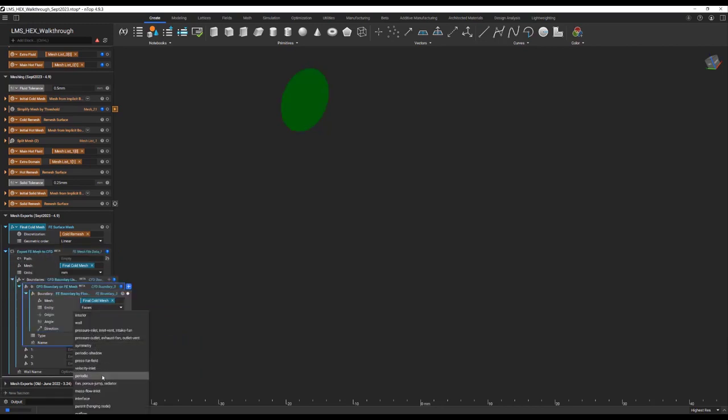We'll select mass flow inlet, and this is a pretty new and big feature, especially when it comes to automation: we can now choose the named selection. Previously, when we would import the MSH file, it would get brought in as a default naming convention. So in this case, it would have been called face set 1. But in this case, I'm going to call it cold underscore inlet.